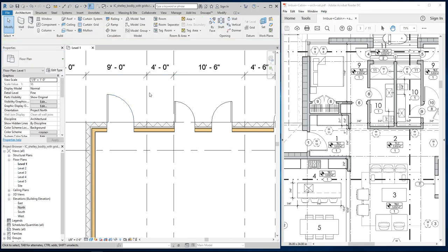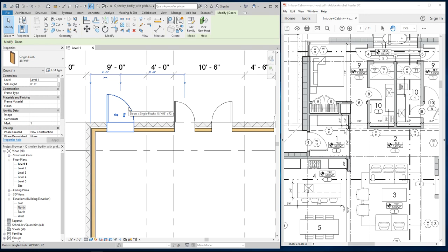Okay. So if I wanted to find, sorry, let me step back. That's how you would create doors with new dimensional quality, right? But what if I wanted to find a glass door or a sliding door, right? A different style of door? Well, it's not going to be very easy for me to take this door and turn it into a slider. Okay, I have to load those new styles into my Revit project, and then I'll use those. Okay, it's like in AutoCAD, you know, you don't take a door like this and explode the block and then turn it into a slider and recreate that block or redefine that block. You just start a brand new block, or you go find one and you bring it in, right?